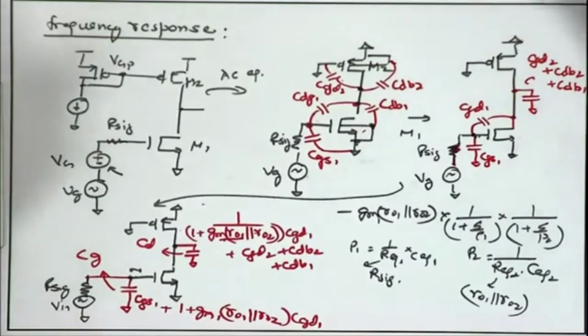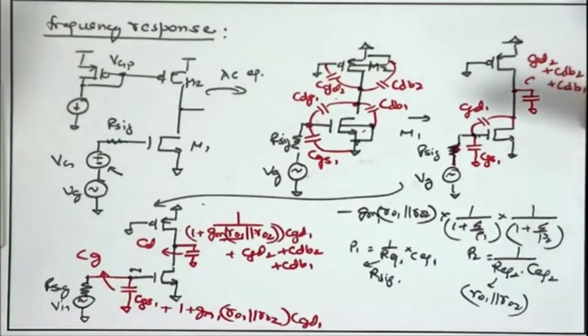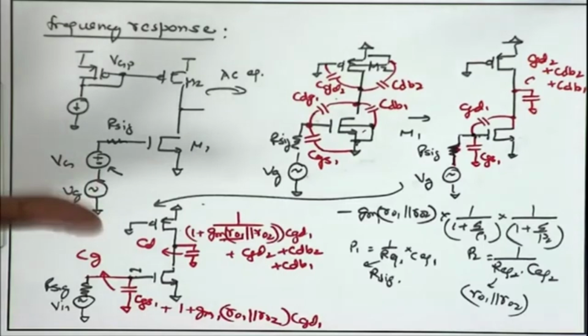So, we will cover how to get the Bode plot and do the stability analysis for multi-pole systems, which we have not covered. Yesterday we just looked into the 3 dB cutoff frequency for a single pole system, and we looked at the 20 dB roll off that happens after the first pole. But in case of multiple poles, once again you have 20 dB, and after the second pole you have 40 dB per decade slope. Those things we will be covering tomorrow when we get to the stability analysis of our feedback amplifier for the front end.